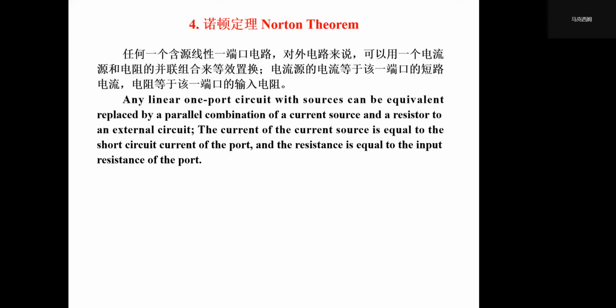The current of this current source equals the short circuit current of this one-port network. Similarly, the parallel resistor has a value of the input or equivalent resistance of the original one-port network.